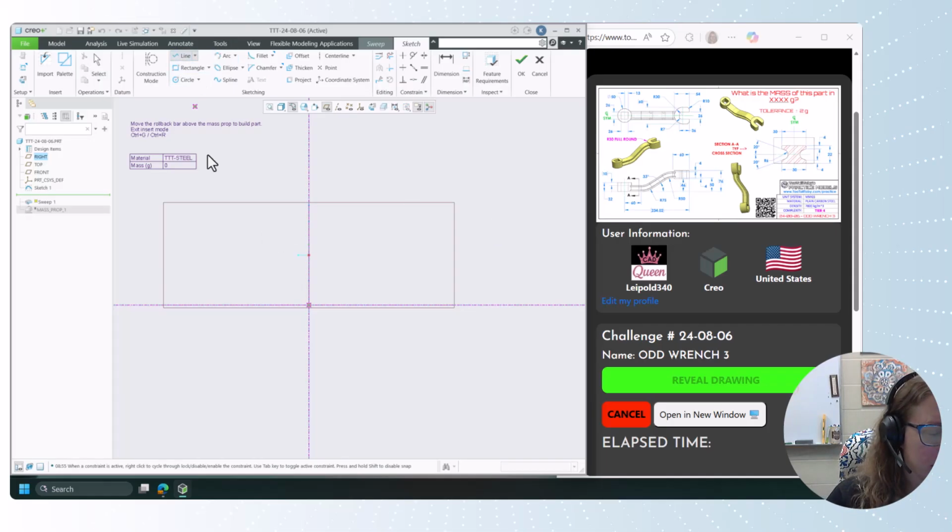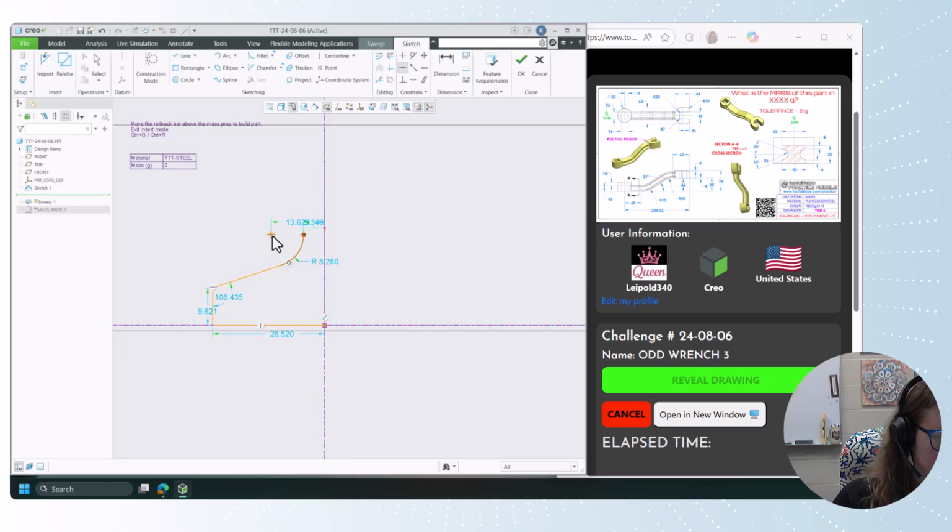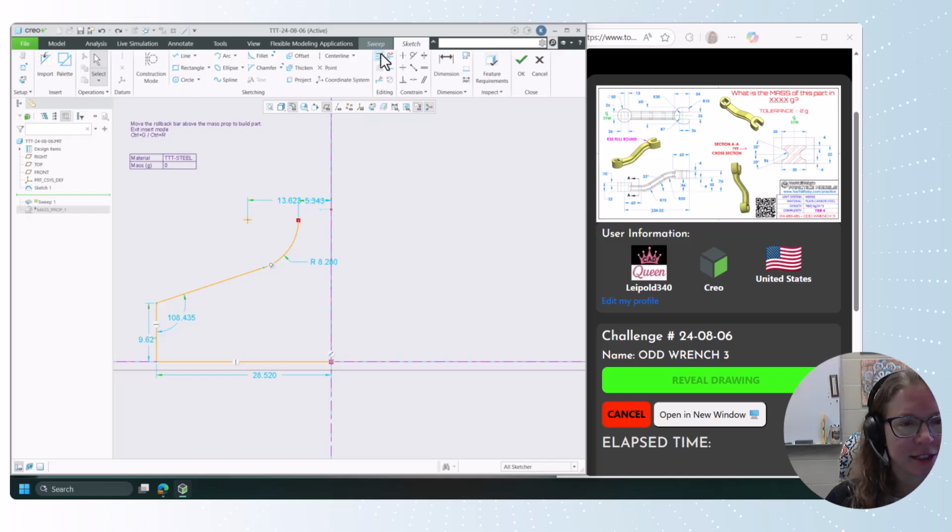Couple of ways to do it. I can come over and up and then angled. And we're gonna have a tangent arc. It's gonna come out and it's gonna stop at the end point. So let's see here. I think I might need horizontal between this point and its center so that I'm getting that kind of, oh, that's actually a funny thing to recognize. It's actually a vertical constraint because I rotated my screen 90 degrees. Anyway,